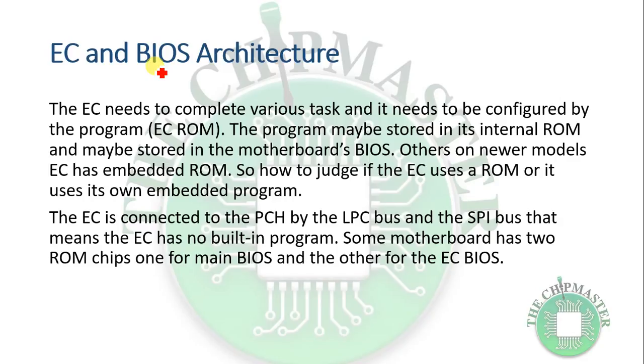So how to judge whether the EC uses a ROM or uses its own embedded program? Right, so if the EC is connected to the PCH by the LPC bus and the SPI bus, that means the EC has no built-in program. Some motherboards have two ROM chips, one for the main BIOS and the other for the EC BIOS. Right, so there are different architectures for connecting the EC and BIOS, and how the chipset, the PCH or the CPU, will read the BIOS. Either it's going to go through the EC or it's going to go through the SPI bus directly to read the BIOS.